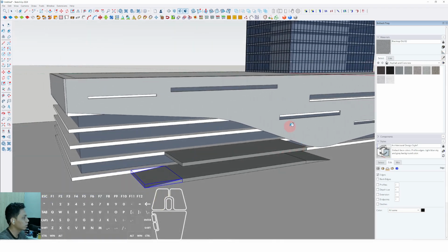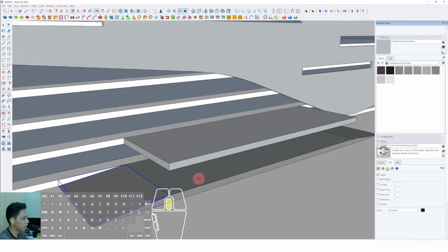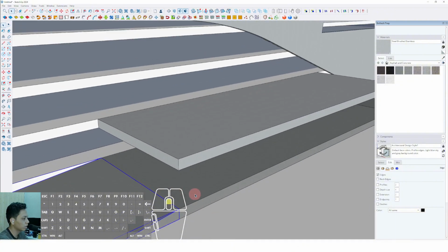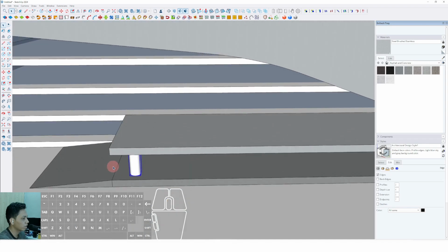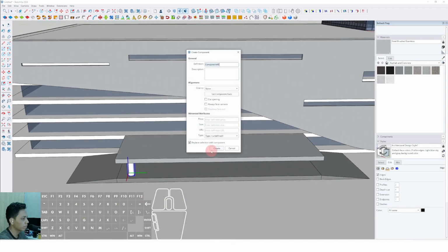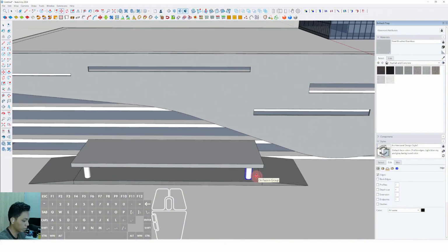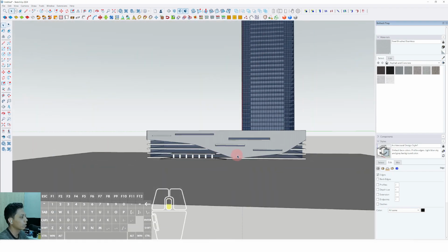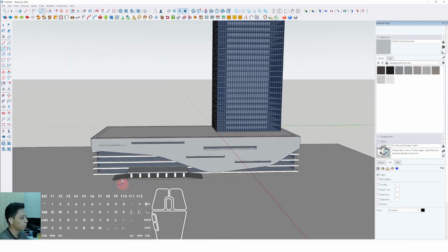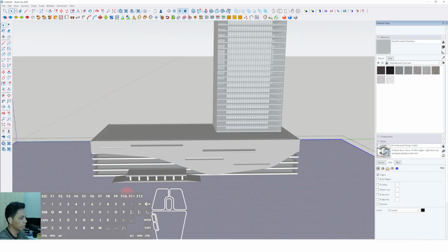We can also add the metal material for this canopy, and we can make another cylinder column to make it more elegant and representative. Select move, press control, press this position, then we can type 6 slash. And also we can make another element such as a landscape area in here. Okay, we can assign for the landscaping area.